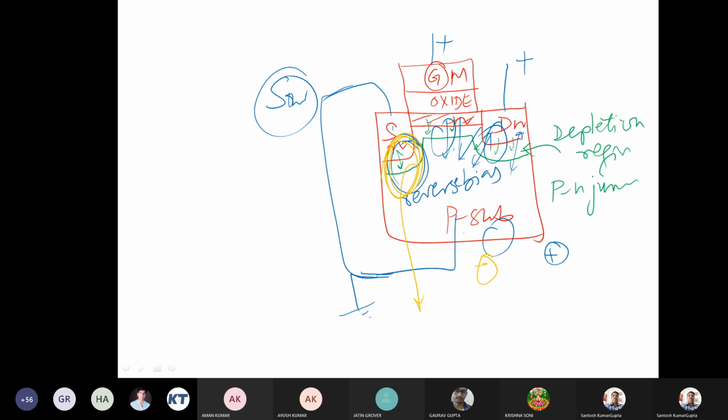And the threshold voltage is controlled by something we haven't discussed here, a potential barrier between the source and channel. That potential barrier is going to change. If we apply a negative voltage at the substrate, then we will need a larger gate voltage to have the same electron concentration in the channel.